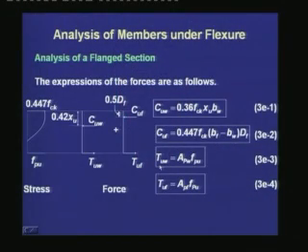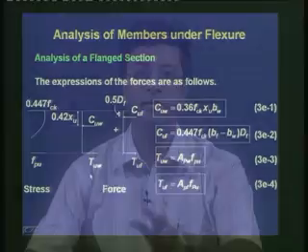Next, the TUW is equal to a component of the total prestressing steel, APW, times FPU, and finally TUF is equal to the rest of the prestressing tendon, which is APF times FPU. And we can observe that each one of these couples are under equilibrium by themselves.